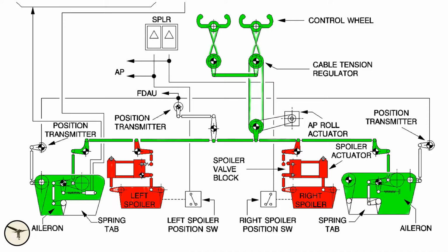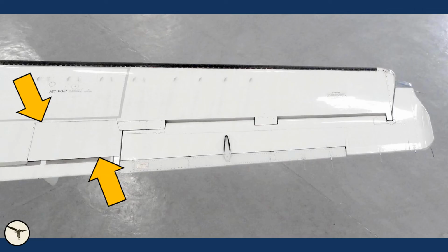The spoilers are operated automatically and actuated with hydraulic power. Only one spoiler can be activated at a time. An indicator in the overhead panel is illuminated when the associated spoiler is not retracted. This indicator is blue on aircraft with EFIS cockpit and green on aircraft with glass cockpit. According to ATR philosophy, blue means manual operation, which is true when it comes to the ailerons. But the spoilers are operated automatically as a response to the position of the ailerons. Therefore, green is the correct color.